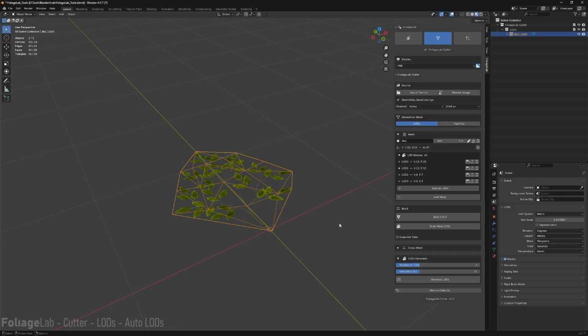The goal of this one is to set the number of LODs you want to generate from the LOD 0. So if you decide to create 3 LODs, you will get LOD 1, 2, and 3. And a reduction percentage, which will reduce the previous mesh by X%. So in our case, by default, we want 3 different LODs with 25% reduction for each. So the LOD 1 will be generated from the LOD 0, the LOD 2 will take the LOD 1, the LOD 3 will take the LOD 2, and so on.